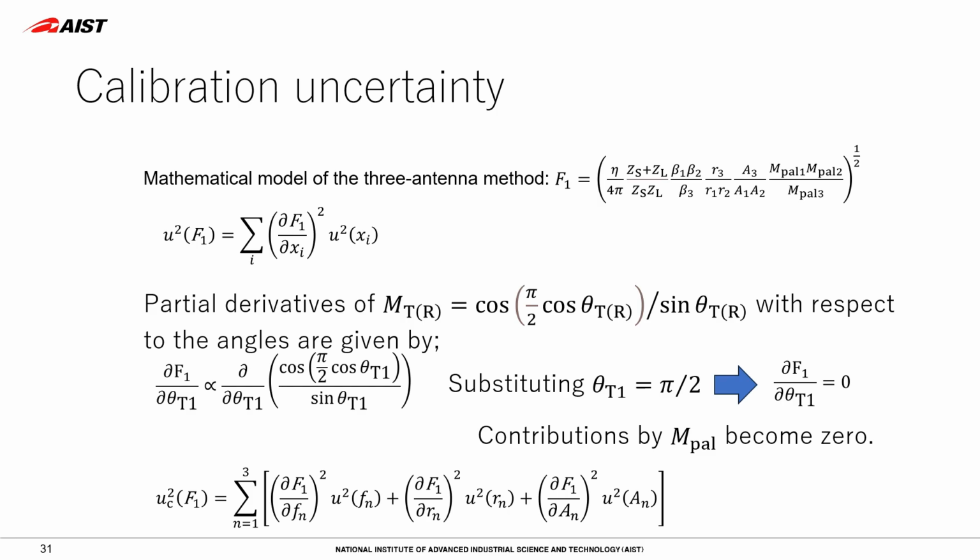Regarding antenna alignment, taking the partial derivative of mismatch factors, the sensitivity coefficient for the angle will be 0. This is true when the antenna radiation and receiving patterns are not highly directional. A dipole antenna relatively has a broad radiation characteristic. This need not be considered. Finally, the effect of the misalignment angles is not included in the ordinary analysis.